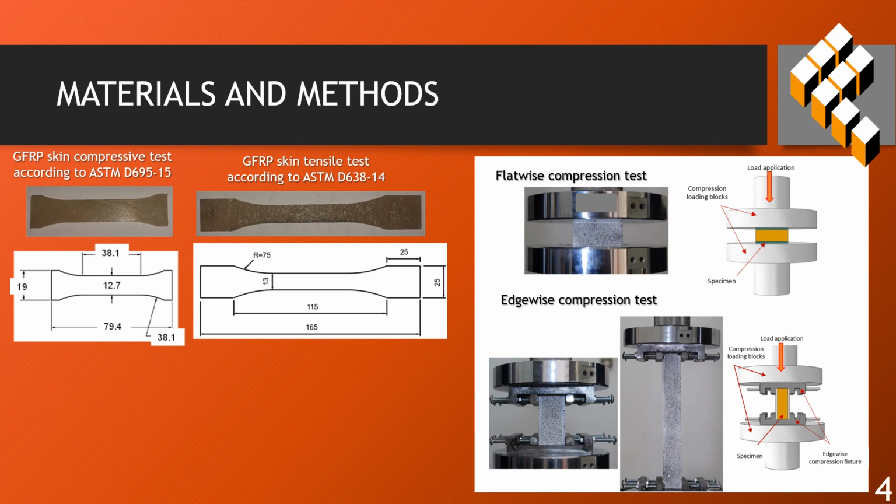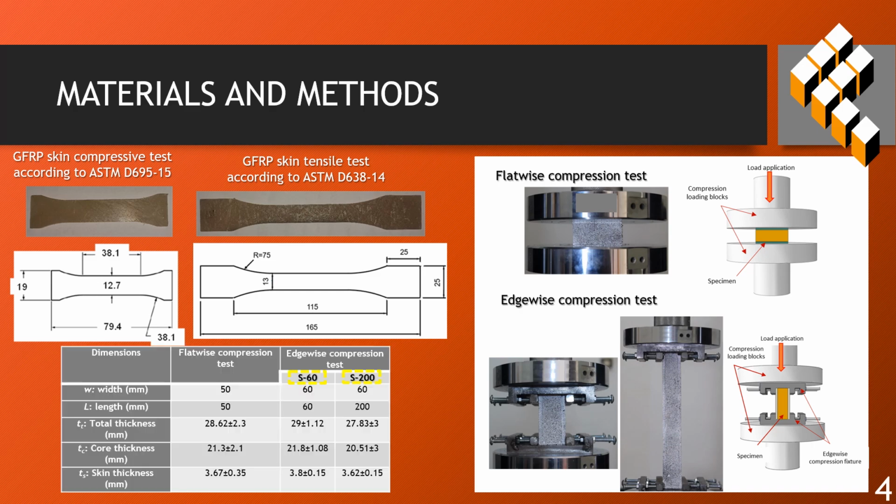To evaluate the mechanical behavior of the sandwich structures, flatwise and edgewise compression tests were performed, as illustrated in the figure on the right. In the edgewise compression test, 2 different specimen geometries were investigated to assess the influence of the length on structural performance.